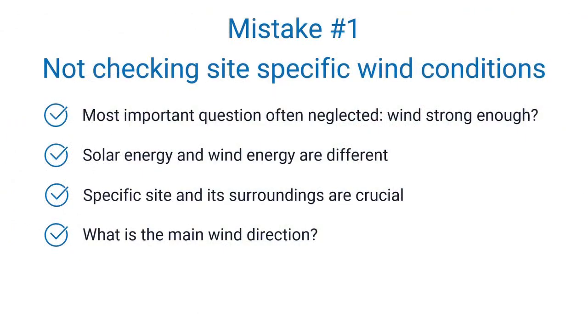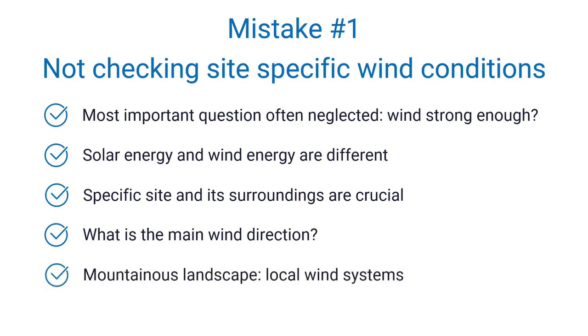So now, last point concerning the site check of wind conditions. If you live in a mountainous region, you have to check specific local wind systems. There might not be an overall main wind direction, but very local wind conditions. This applies for countries like Switzerland, where you have lots of high mountains and deep valleys.